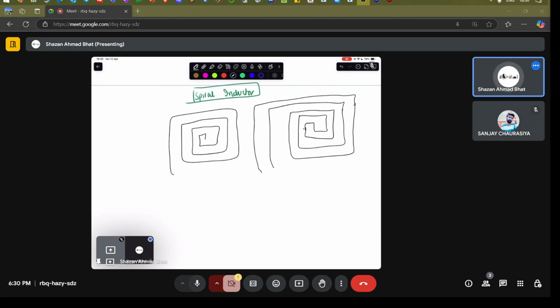So this is basically the thickness of these metallic lines which are deposited and will behave like an inductor. Everything is going to matter: the spacing, the thickness, and this particular dimension, because there will be current flowing in the system. Let's say the current is flowing here in this direction, in this direction, and here in the opposite direction. Whenever the current is flowing in the same direction, it will basically reinforce the inductance.